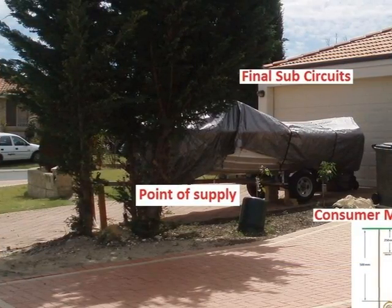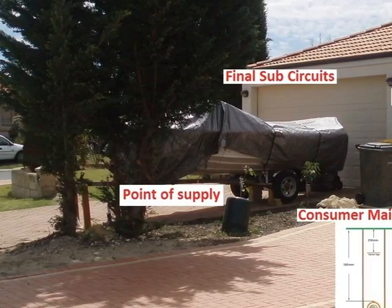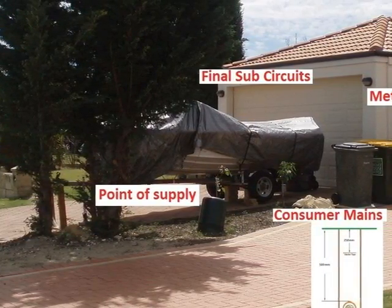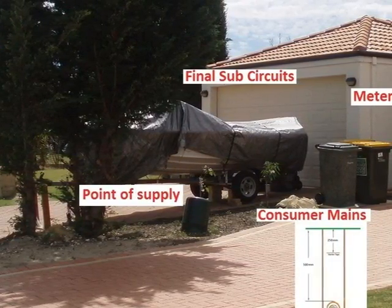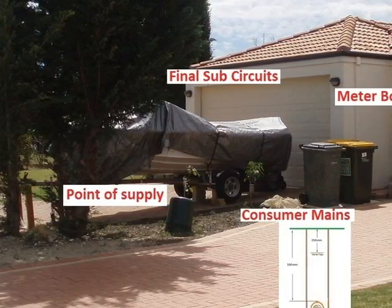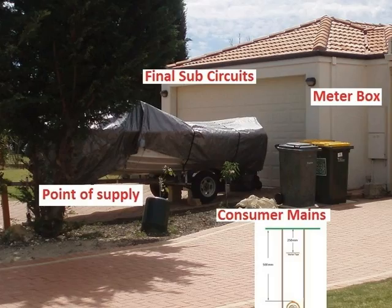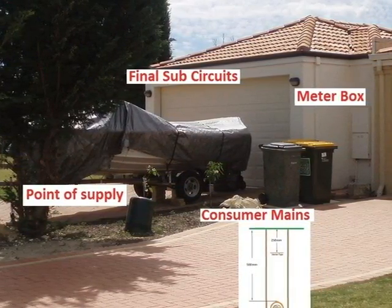For customers' cables, we're dealing with the cable running from the point of supply. That could be at a mini pillar for underground supply, or it can also be the point of attachment. If you look at the WA electrical requirements, you'll see the variations on the point of supply. Then from the point of supply through to the meter, the meter box, the switchboard, and then from there going out to various final sub-circuits and also sub-mains.